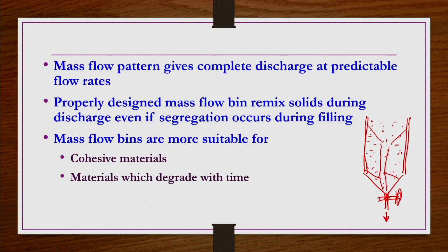What happens is the material just above the opening passes out, and it forms a vertical column like this, and the material comes out through columns like this. So the top layer material goes out through this column only, whereas the material at the bottom, which reached first while filling, goes out very last. So these kinds of problems are there.